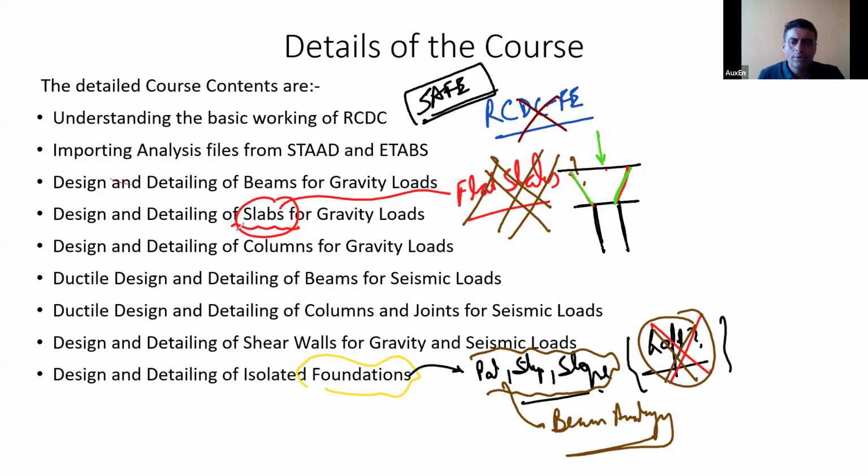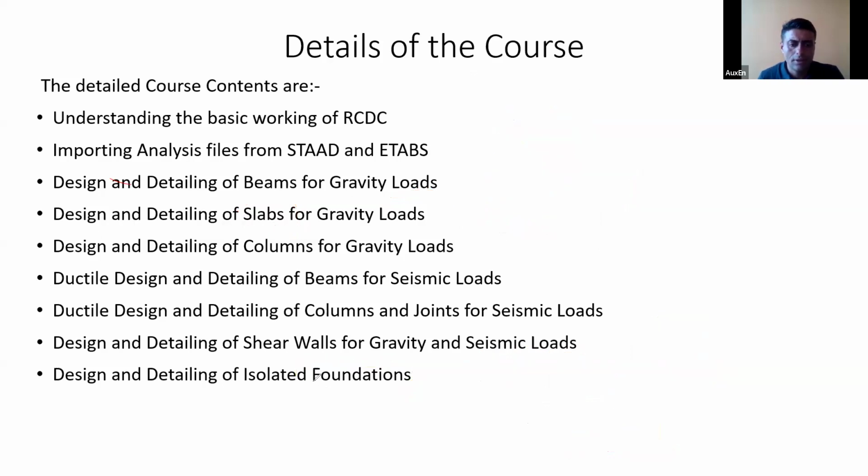So rafts it cannot do, flat slabs it cannot do, so then what can it do? If it cannot do flat slabs, if it cannot do rafts, basically you can use RCDC mainly for your framed structures. For framed structures, I would say it will be very well suited. So RCC frame structures will be very well suited.